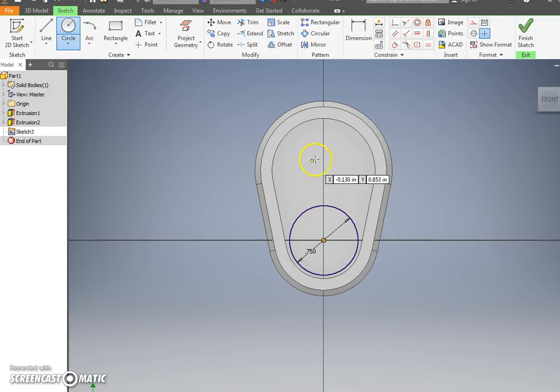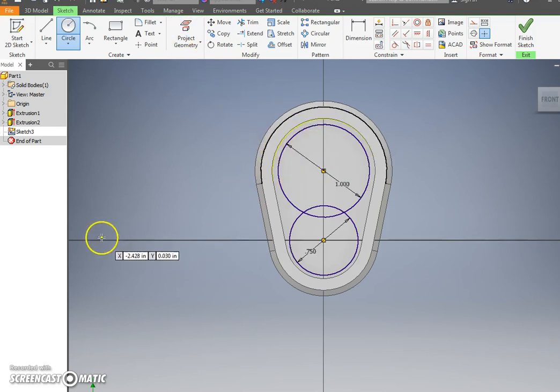Simple enough, right? Well, up here, I want to find my midpoint, but I could do a project geometry, but instead I'm just going to hover over this circle. It gives me my center. Press 1. Okay, so that's a really easy way to save a step and not have to go project to find it. I love that tool.